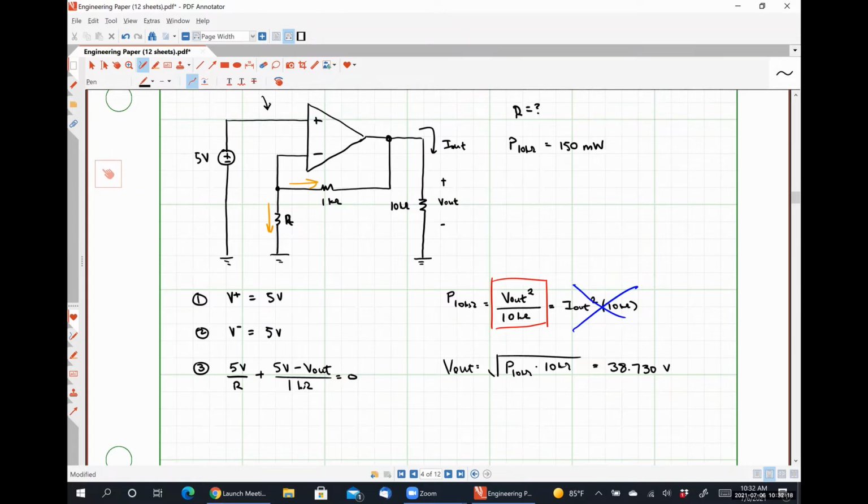You may not have recognized this yet, and it's something we'll talk about in just a few minutes, but whenever we apply a voltage to the non-inverting input terminal, our output voltage has always been positive. And whenever we have applied a voltage at the inverting input terminal through some resistor network, our output has always been negative.